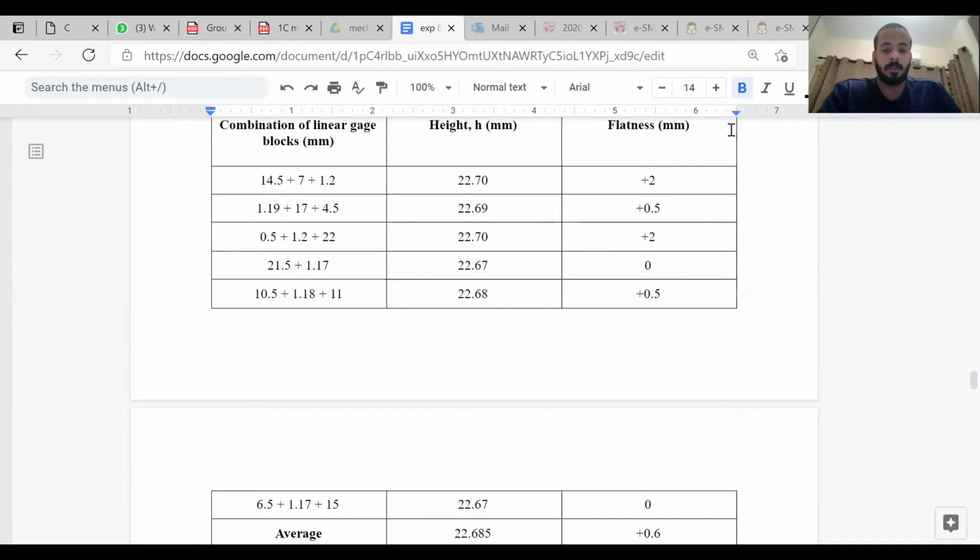The main cause of the percentage error was probably the condition of the equipment, since the equipment was quite old. The flaws, especially the rust, can affect the height of the sine bar. Other than that, the vernier caliper that had been used to measure the sine bar may not be in perfect condition, so the reading shown on the measuring instrument must be affected also.